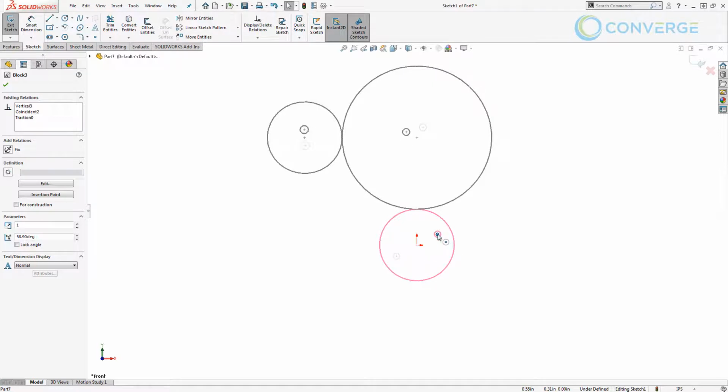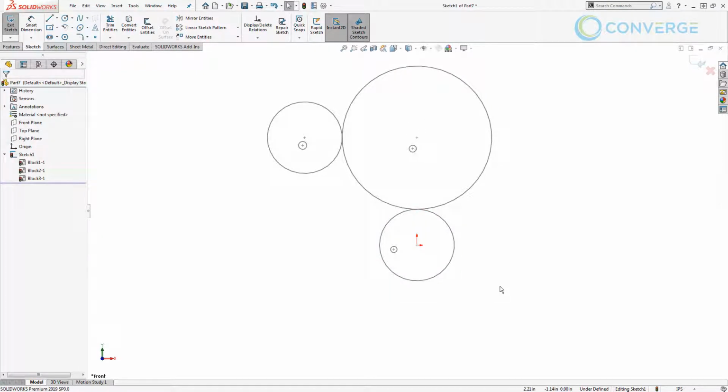And again, we're dealing with 2 of them that have a 2-inch pitch diameter, and we have 1 of them that has a 4-inch pitch diameter. So the 2-inch ones will be rotating the same amount, so 1 revolution each. However, the 4-inch pitch diameter is going half of that amount every time we rotate. Very similar to our belt and pulley example where we just looked at the diameters of these circles.